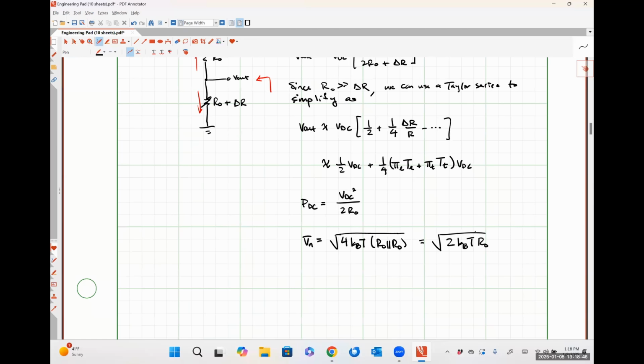So we've eliminated the temperature dependence problems of our resistivity by this particular configuration. We've actually lowered our noise spectral density, but we've probably increased our power consumption. I say probably because it's not an apples to apples comparison, because we don't know what IDC is or what VDC is. We're just using things generically here.